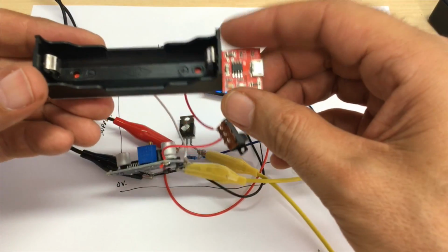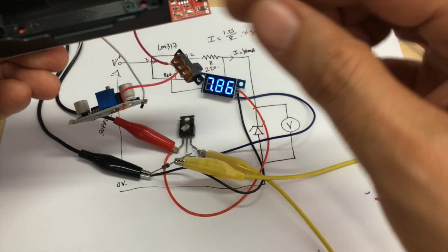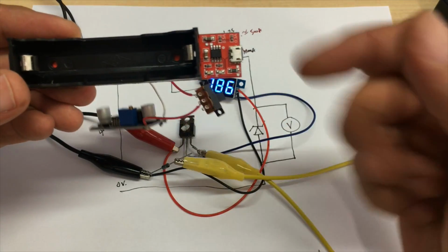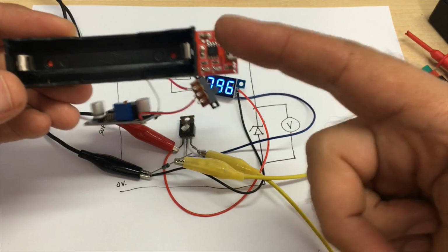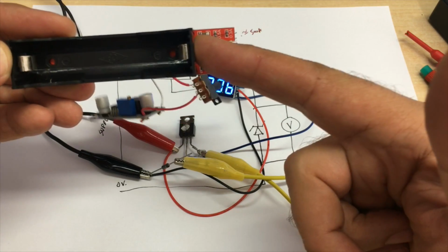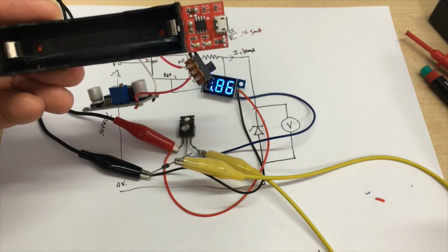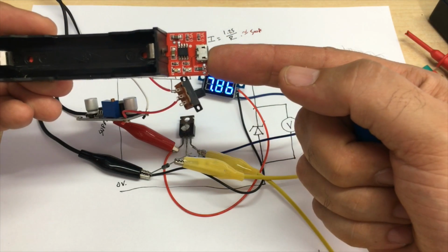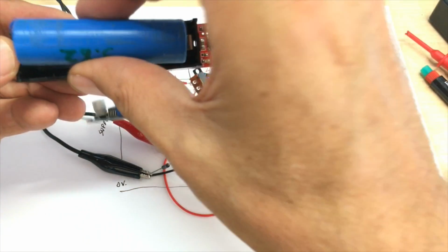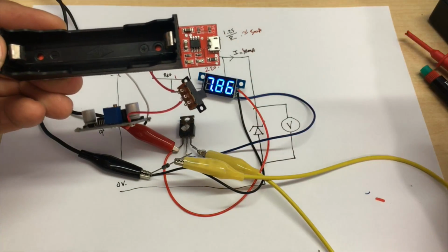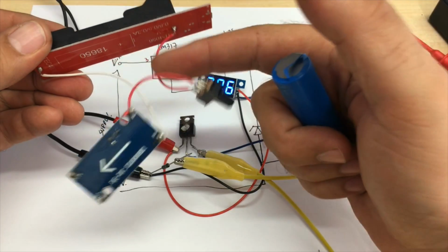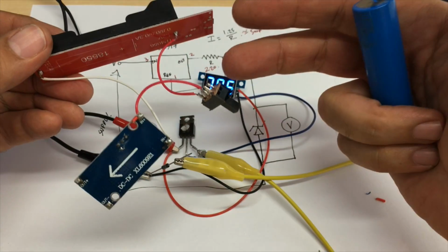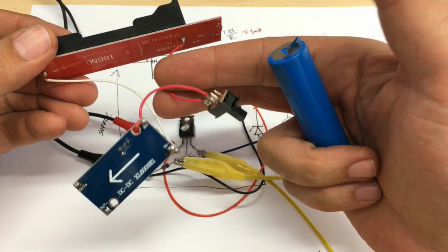Then using one of these modules, again another module, this thing actually is a USB charger module for that, and all it does is it provides me with a socket for the actual cell, and it provides me with the charging circuit using micro USB. So if I put the cell in there and I want to charge it, I can charge it through that. Then I have the voltage coming out here, which is anywhere from 3.8 or whatever to 4.2 volts.